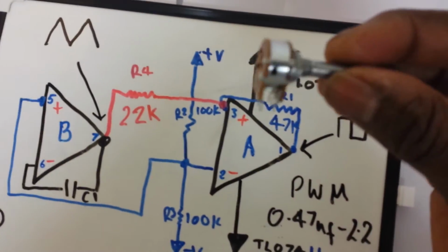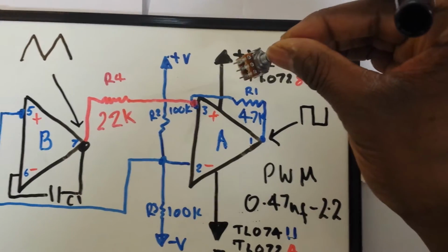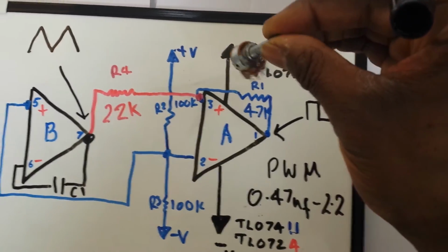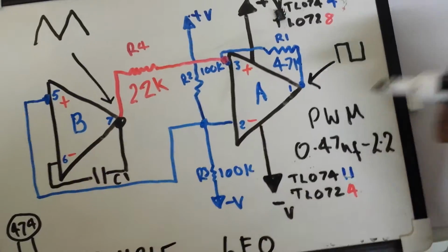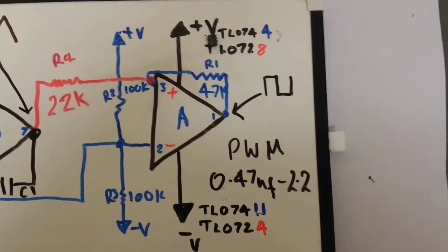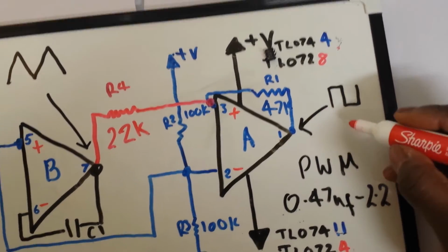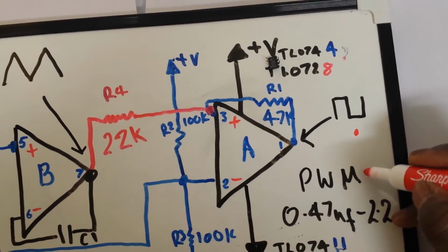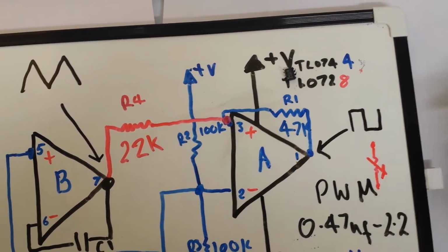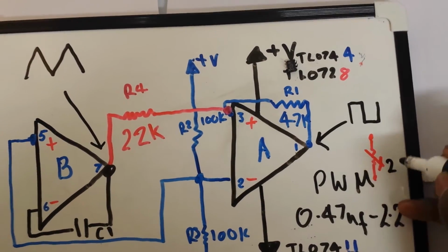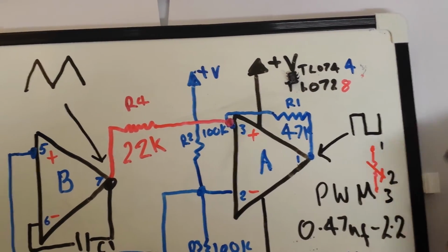We can either go for something like a 470K, or we can go for a 1 megaohm, which I've used pretty much on all my LFOs, and which gives us quite a bit of range. Now, something very important which I discovered down the line of building this synthesizer: we make this our potentiometer, and we'll call the wiper the middle pin 2, and we'll say that's pin 1 and pin 3.